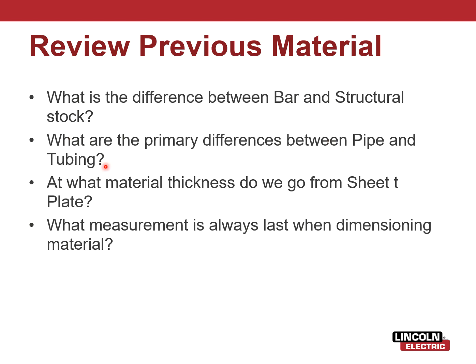We should know at what material thickness we go from sheet to plate. A little typo there. So what is that threshold? Remember, is 3/16 considered sheet or plate? It's plate. 3/16 and above is plate, so less than that would be considered sheet.